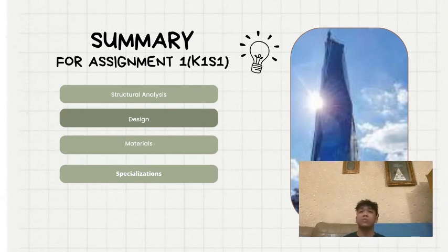The structural system of this building is complicated. It is like a crystal that is formed by many triangular pieces. Merdeka 118 comprises 8 mega columns and central core walls, intermediate columns, 3 sets of single-story belt trusses, 3 sets of triple-story belt trusses and 3 sets of triple-story outriggers.